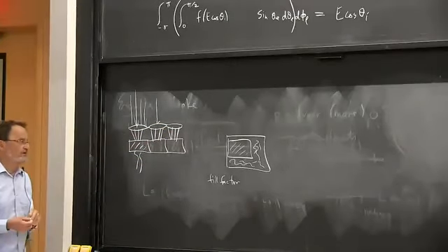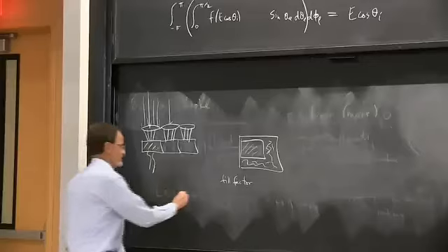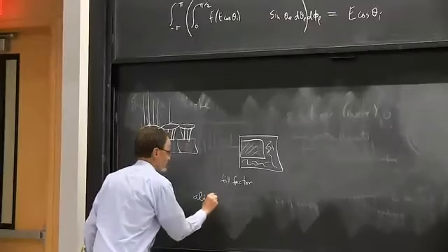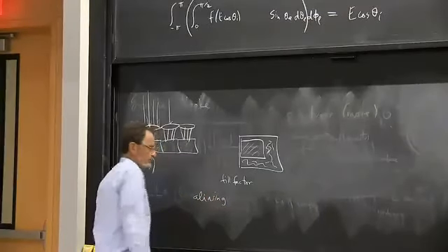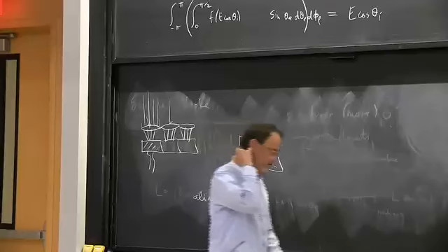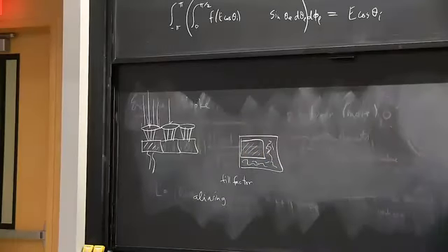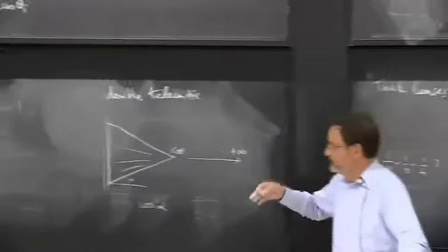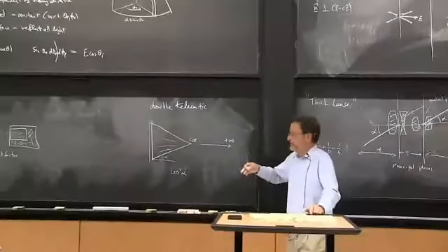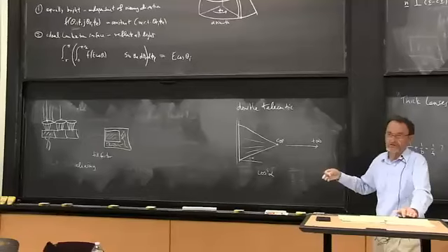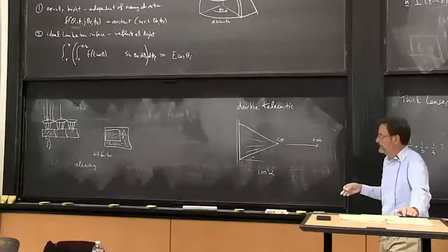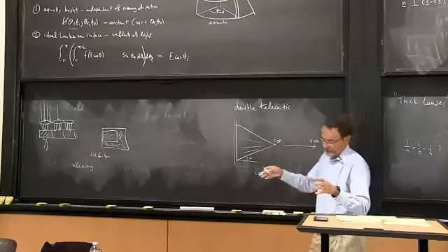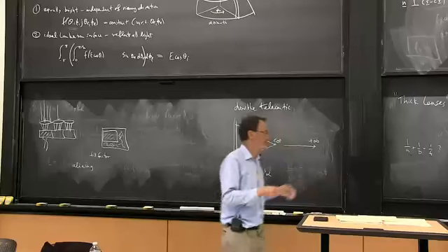The other reason is aliasing. Those of you may remember in 6003 or some other equivalent signals and systems course that when you sample discretely, you have to be sure that there aren't high-frequency components in the signal. And in our case, we could have sharp transitions in brightness from one area to another.